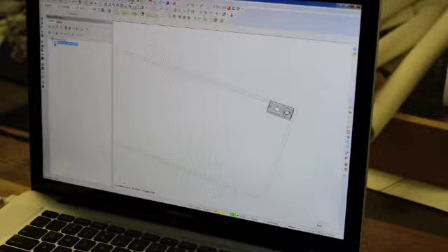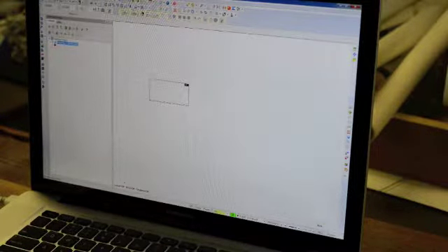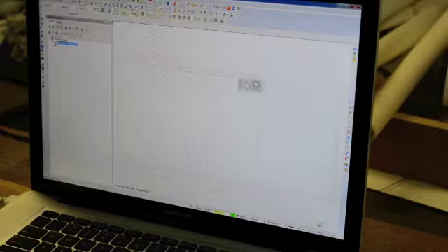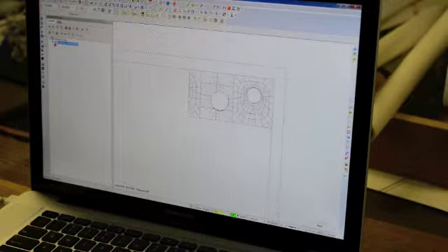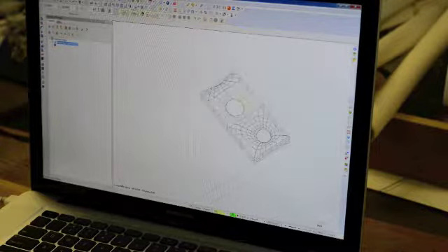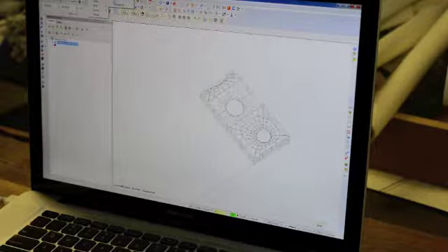When you create toolpaths, you should always be in the top view. One of the common problems you run into is sometimes you won't actually be in top view, and you'll have done everything perfect and you're just struggling to figure out why. If you look down here or in the toolpath we set up itself, this should be in top view. Another thing to always make sure of is that your machine group is for a Thermwood, because that's what we have downstairs. If it isn't, you'll have to go over here, Mill, and pick Thermwood from there.